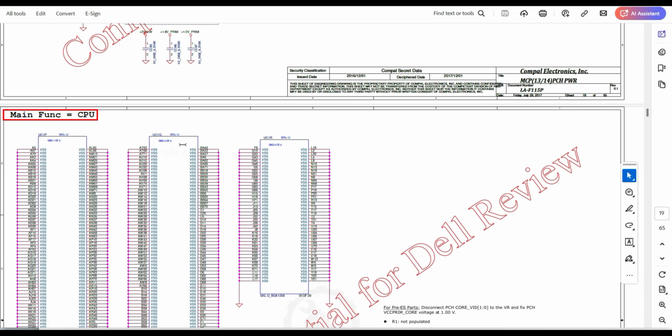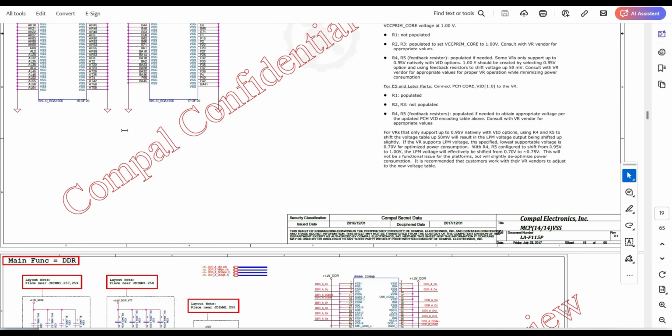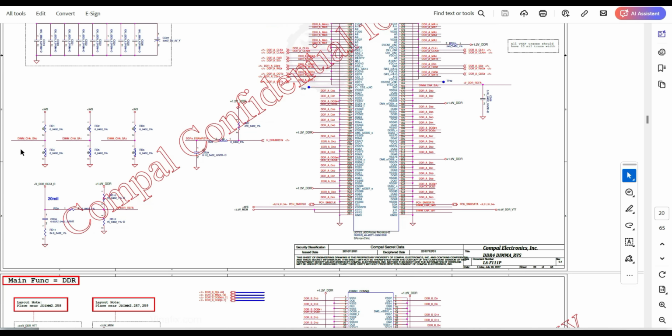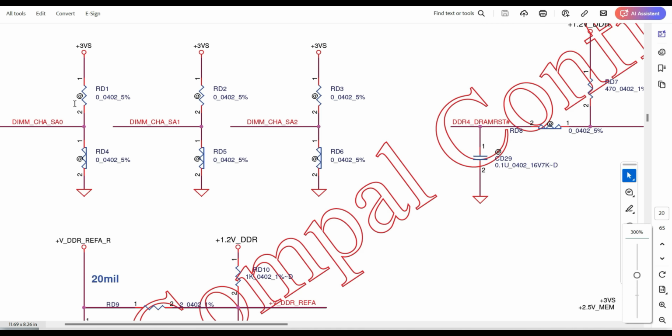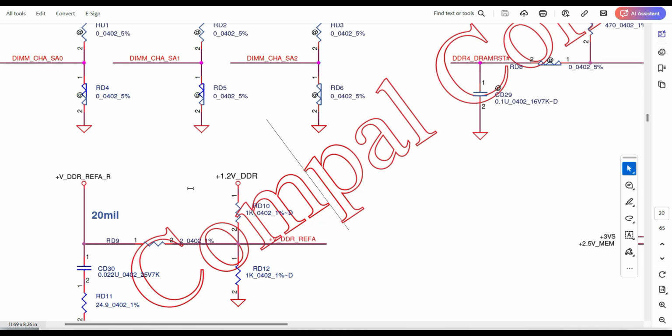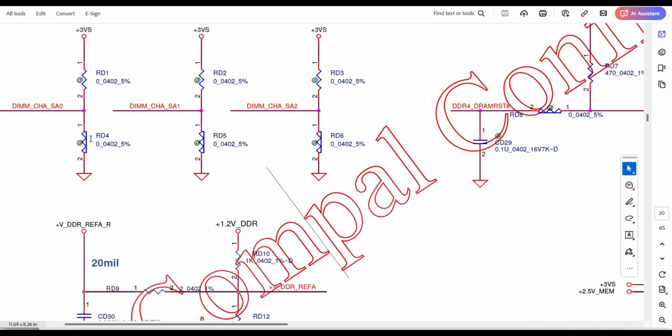See all this, these are the ground, there is a resistor here. See, these are voltage dividers or pull up or only pull down depending on the condition. Okay, see 3 volts you will always get here in case the component is present. You won't get the voltage in case the component is absent. That's it. Here it's connected to ground, there will be no voltage here, because this condition may be a resistor or it may be directly a jumper.